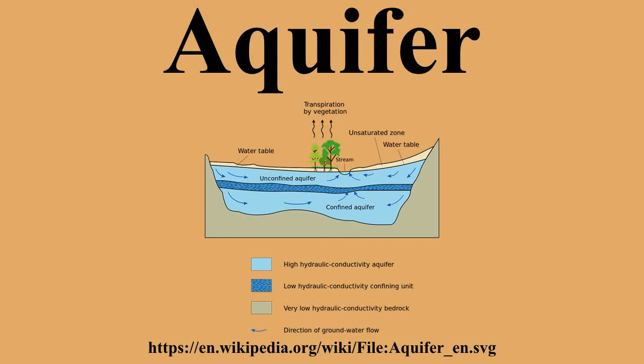The normal capillary rise in a clay soil is less than 1.80 meters but can range between 0.3 and 10 meters. The capillary rise of water in a small diameter tube involves the same physical process. The water table is the level to which water will rise in a large diameter pipe that goes down into the aquifer and is open to the atmosphere.